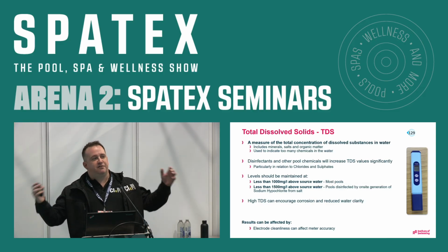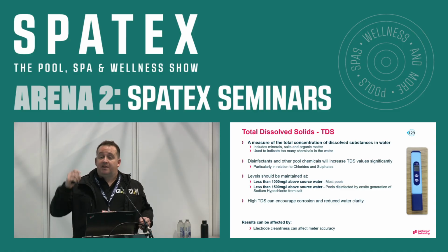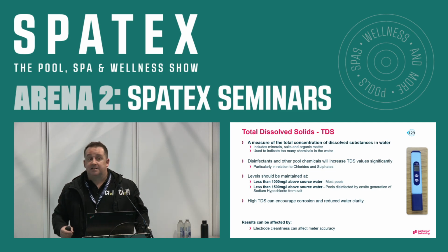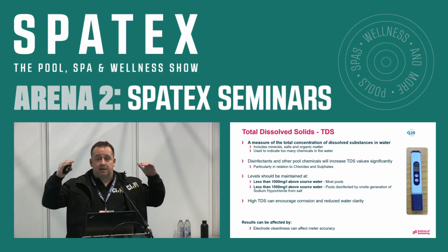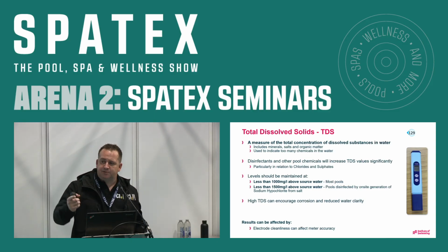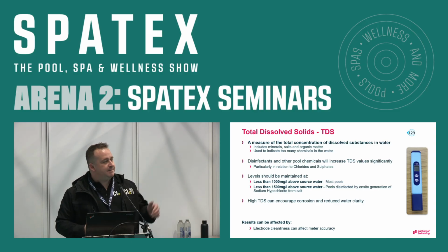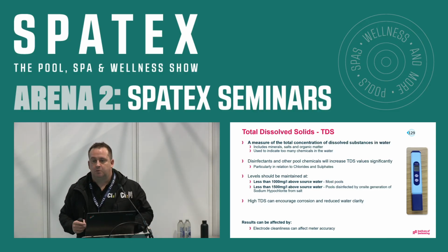And they bring all their filth and all their chemicals and all that kind of stuff. So the TDS goes up again. And then our dosage control unit responds by adding more chemistry in. So our TDS, if left uncontrolled, will just slowly climb. Remember the 1,000 over source. If I've got 200 coming through the tap, or 300 or 400, whatever, I add 1,000 to it, and that is my limit.